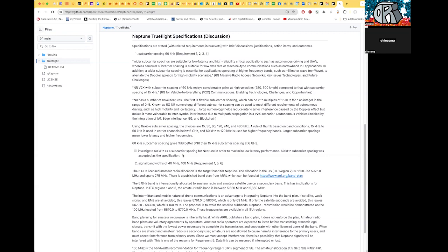In other words, we talked about adaptive coding and modulation with respect to our DVB-S2 work, where depending on the signal to noise ratio, you modify your coding and your modulation in order to just ride the capacity curve. That's how it's done, and it's really neat. It does require some complexity and some agility, but you change your coding and your modulation in order to take advantage of better or worse channel conditions to deliver the most amount of bits possible. That means your symbol rate stays the same, and in our case, our symbol rate is staying the same. It's just how many subcarriers do you add.